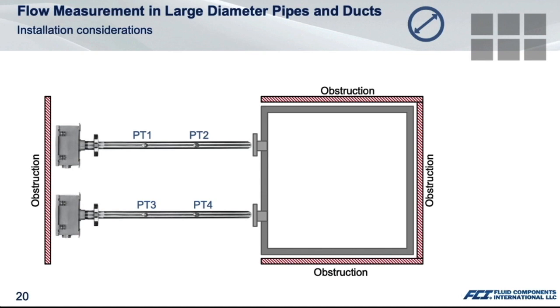When you work with the manufacturer to determine the certain flow elements and the length of the flow elements, as these are always customized per application, make sure to consider that obstruction which may be occurring at the opposite side of the process connection. There should be sufficient clearance between the process connection and the obstruction which you have found in the installation.